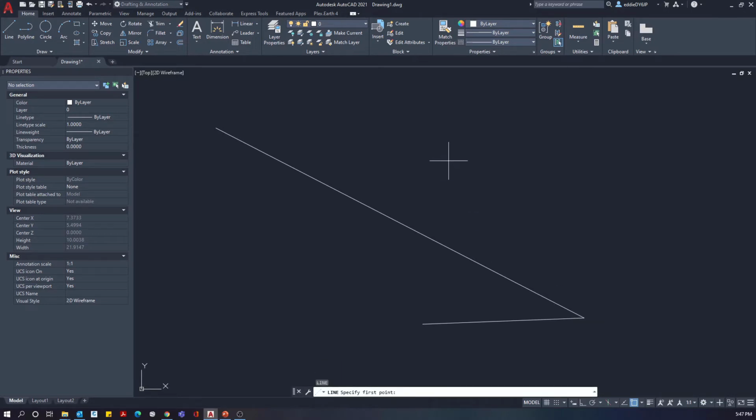Let's look at the next one, the midpoint snap, and as you can see, when I get to it, it is a triangle. So there are going to be different symbols as we use different types of snaps. Now let's look at the perpendicular. If we draw our line here, as you can see, it tells us where our perpendicular line should be by giving us that right angle symbol. So we come over here and we click and it snaps.